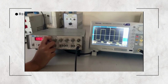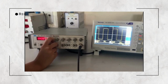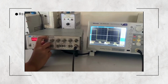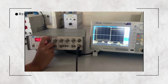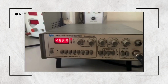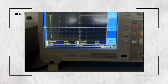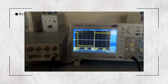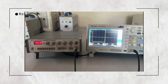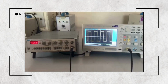By decreasing the frequency, we can see an increase in the time period for the graph for the positive and negative half cycle. As we continue decreasing the frequency, the cycle length increases and our amplitude remains constant. You can also see our applied frequency and peak voltage on the DSO. We will just auto set our DSO for getting a proper waveform.